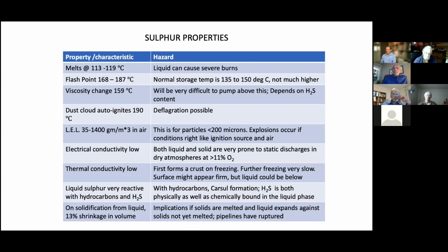And I've heard of stories where they poured big blocks, and 15 years later, as they've been trying to reclaim the blocks, excavate the blocks, they've come across molten sulfur. And where this is important is when you're pouring sulfur to block, you have to only pour it in very thin layers. If you start pouring it in very thick layers, you could very well have molten sulfur underneath. And this has happened where the operators who are on top of the block trying to squeegee the sulfur around have sunk into molten sulfur.